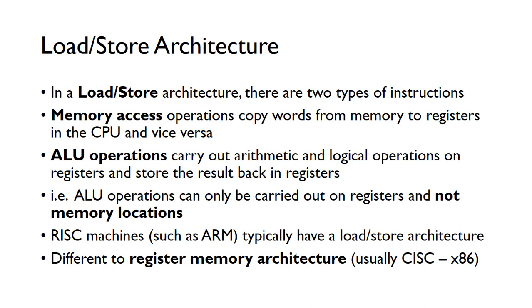A RISC machine, such as the ARM Cortex microcontrollers, as I said before, most microcontrollers typically have a load store architecture. This is different from a register memory architecture. There are usually CISC machines, complex instruction set computers, which can access memory directly as well as the registers.